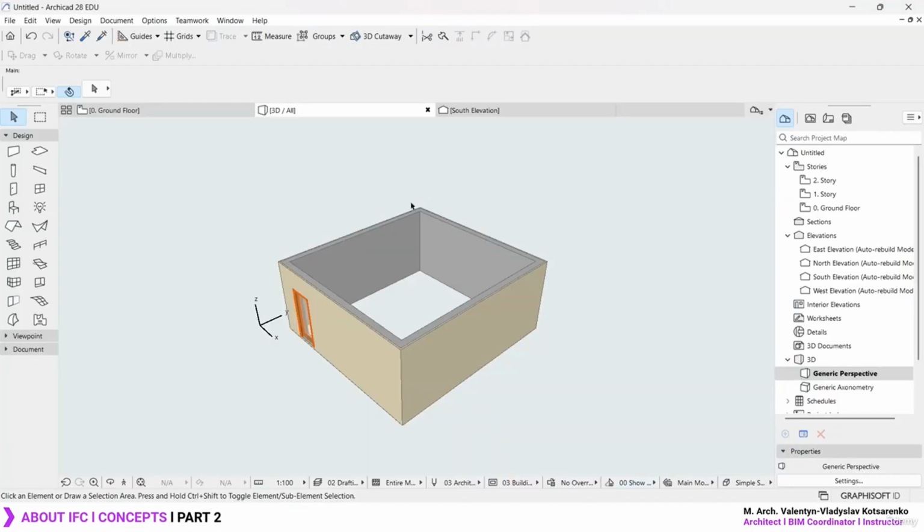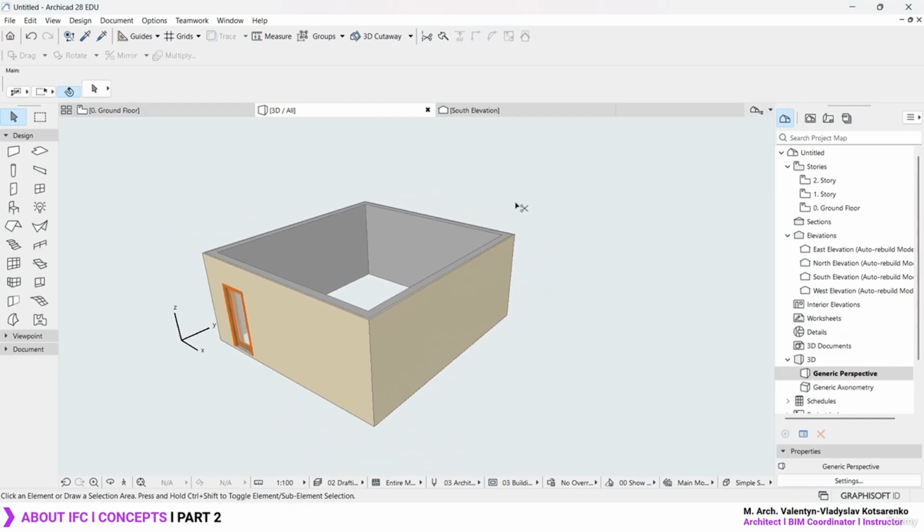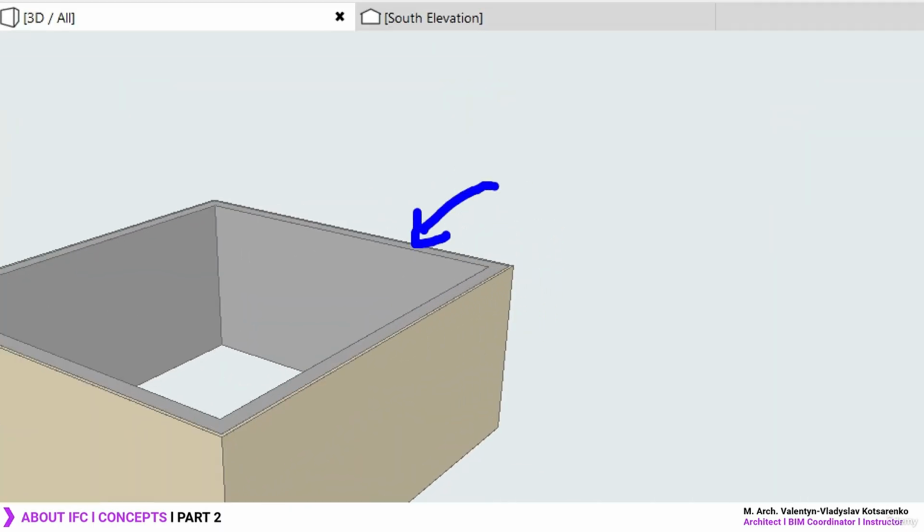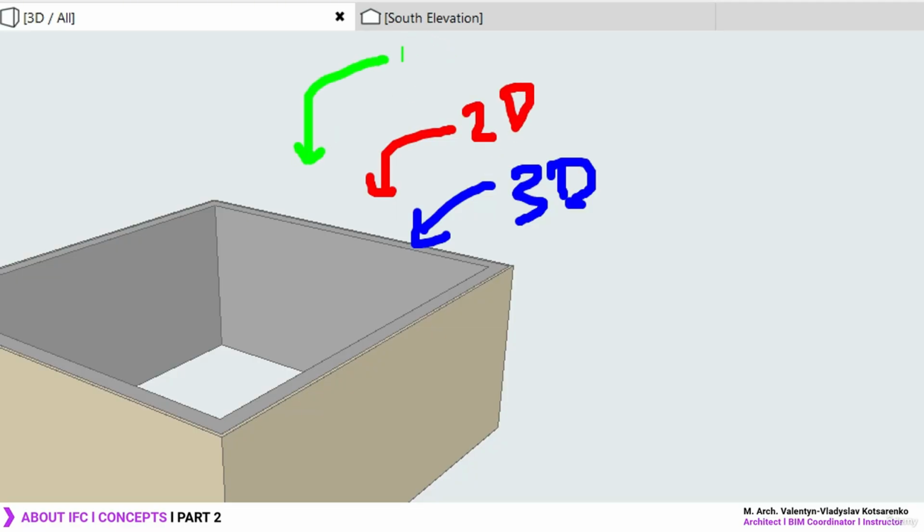Which type of information can we add into IFC? Pretty much everything. We can add the whole 3D elements we got visible. We can add 2D information, most of the 2D information, not everything. And also we can link a bunch of metadata and properties into the IFC format. But pretty much each software will map the information from the native tool, the native database, into the IFC format, so other software can convert this into their own